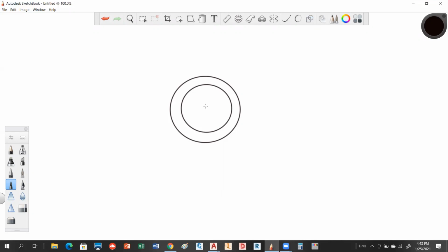So what you're going to define is what's called an outside diameter on this guy. Okay, so you'll define an outside diameter, and then you're going to define an inside diameter. And once you do that with the donut, then you just place the center point. And what it's going to do is generate those. If you have this filled on, then you're going to see this filled in here. All right, so the name of the command is donut.